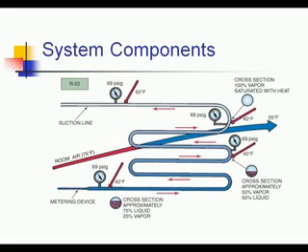It absorbs heat from the medium being cooled, evaporates the refrigerant into a 100% low pressure vapor. Remember, as we boil anything, we absorb heat. So the evaporator is absorbing the heat from the actual metal of the evaporator, which then absorbs the heat from the surrounding space. The liquid line that we're talking about carries the high pressure refrigerant from the condenser to the metering device.